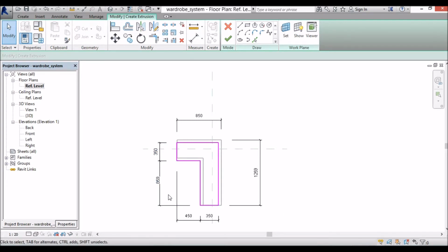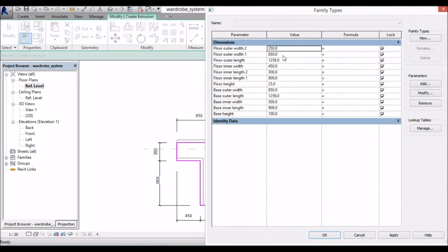Now we will apply parameters, and I'm just going to actually adjust the value for that parameter because having put in the dimensions on this side, I can actually see that I had 909 as the length there. I only want it to be 859. So in my parameters here, mistakes are fantastic because you learn from them.